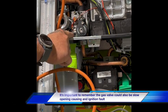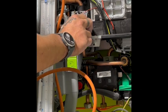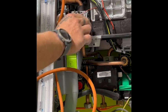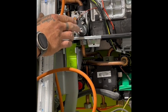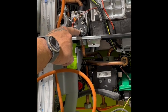Depending on what boiler it is, it could be that the gas valve is an adjustable gas valve and the high and low CO2 settings are out. So we'd start looking at other parts of the ignition sequence before we start messing with that gas valve then.